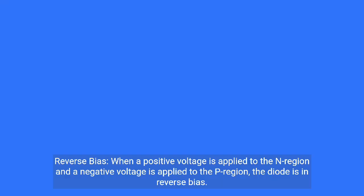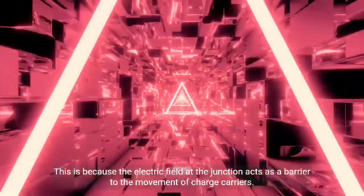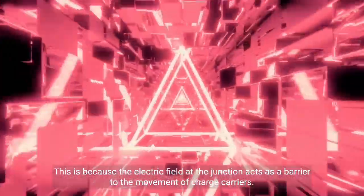Reverse bias. When a positive voltage is applied to the n region and a negative voltage is applied to the p region, the diode is in reverse bias. In this condition, the diode blocks the flow of current, except for a small leakage current. This is because the electric field at the junction acts as a barrier to the movement of charge carriers.